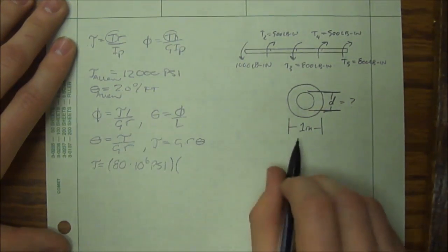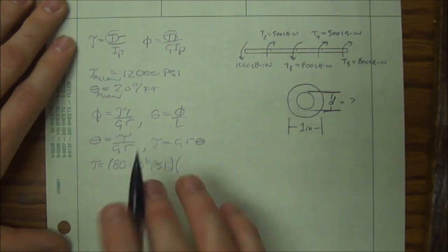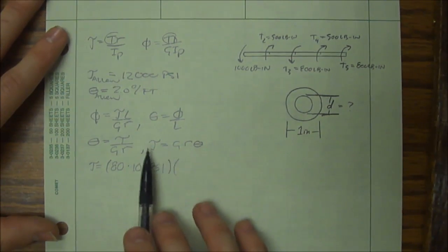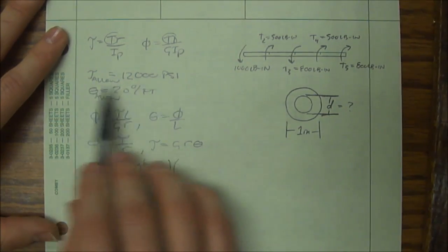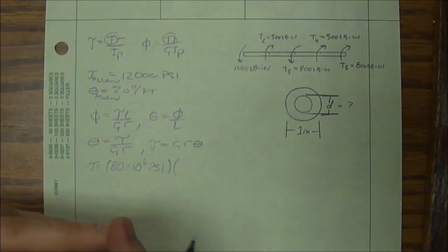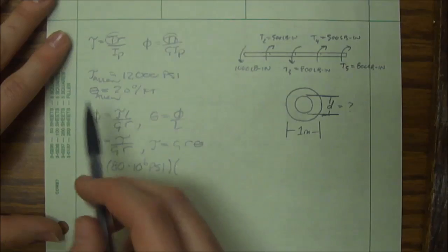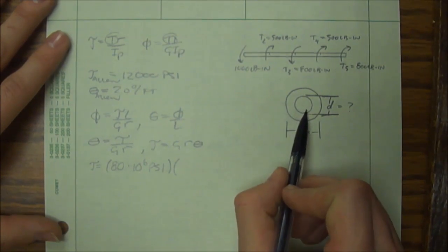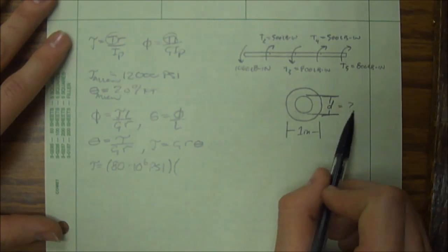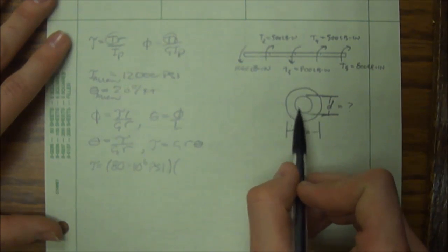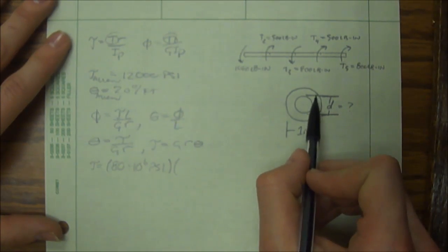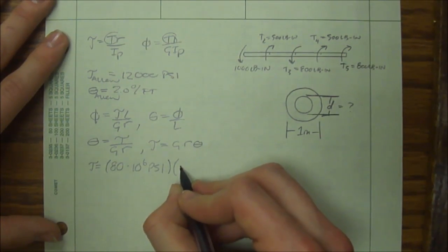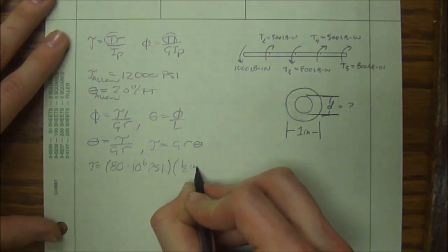A radius, we have an outer radius. Here's my thought process as far as radius. I'm trying to get my limits here. I'm trying to find what's going to break my rate of twist first. So my inner is going to be a little more conservative. I don't even know that anyway. But even if I had it, I would want to use my outer radius. That's going to give me my greater shear stress. So that's going to be, well, 1/2 inch.